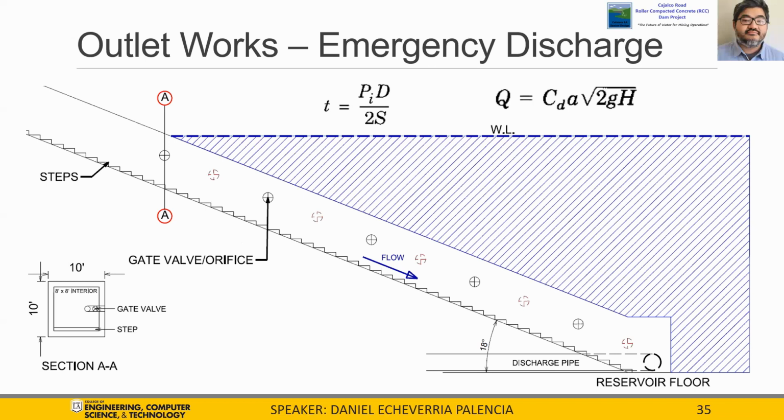Using the Design of Small Dams manual, our pipe was sized to be 1.5 feet in diameter, but we increased this to 3 feet to allow someone to enter the pipe for maintenance. We chose to use ductile iron due to its strength and its low cost. Using the American Water Works Association manual, M41, we determined a minimum pipe thickness to be 0.31 inches using internal pressure.